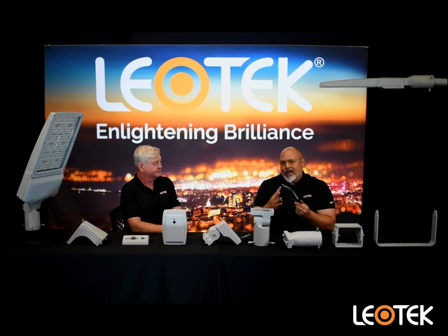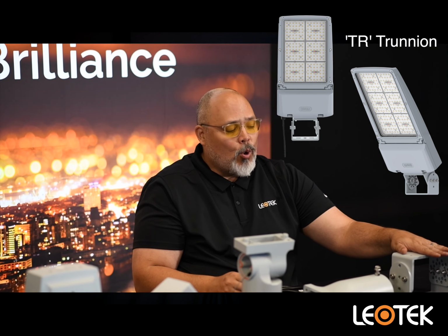It's a little detail, but it does save a lot of time in installation. Some additional mounting options that we have are our Trunnion mount and our Yoke mount. They're very similar. I will say the Trunnion mount is probably a little bit more robust. So if you're going to be mounted to a structure that's subject to vibration, like maybe a bridge, you're going to want to use a Trunnion.